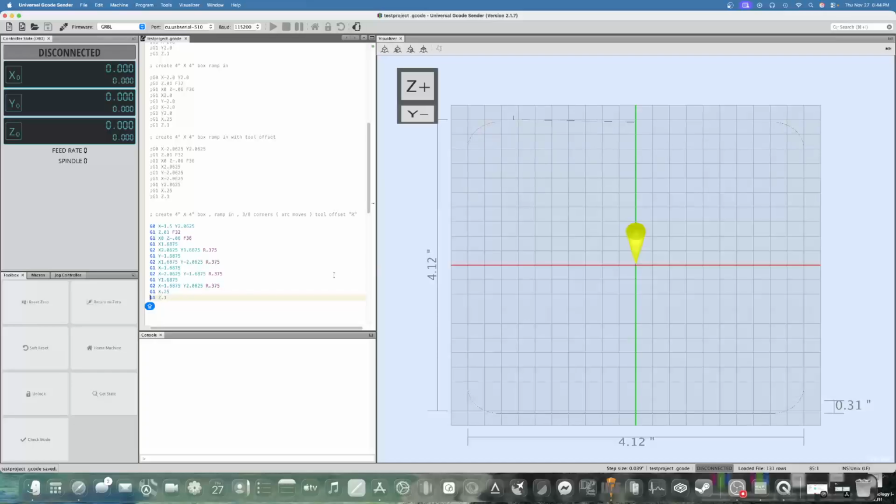Actually, this is basically the same as this one. It's offset for the tool width, just instead of having the square corners, we've got these radiuses here. Now these are 3/8 radius. Let's get up here to a move point. That's speeding over, that's speeding down to start, that's to ramp in. Now you notice here, I stopped at 375,000 shy of 2 inches because that's where the beginning of my radius is going to start.